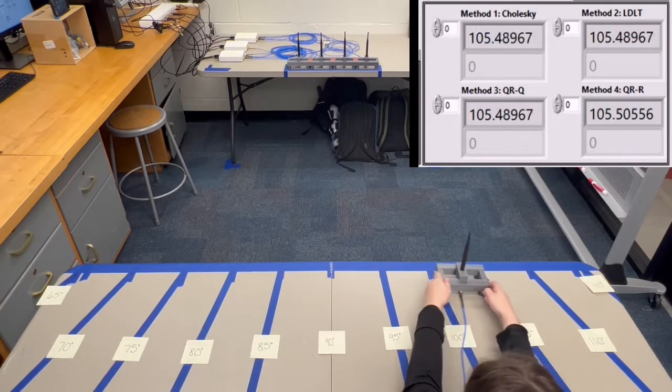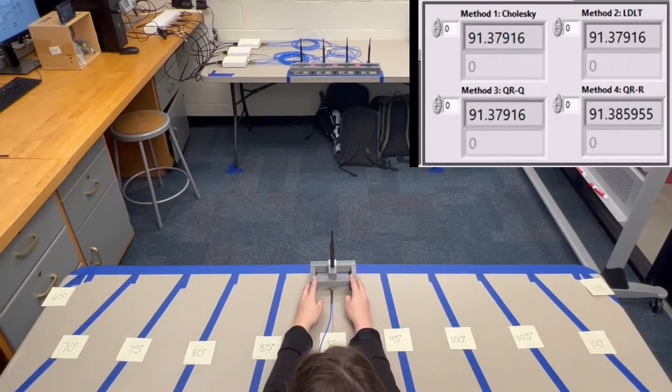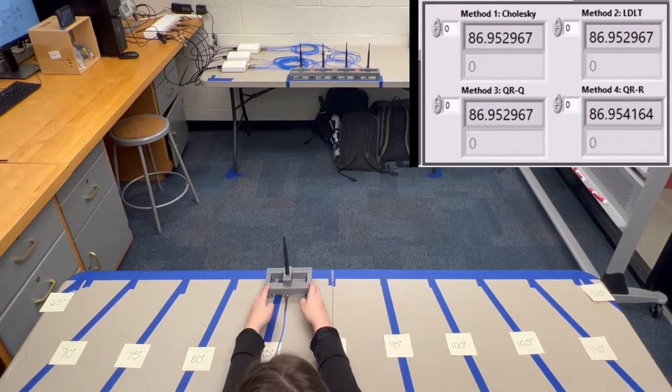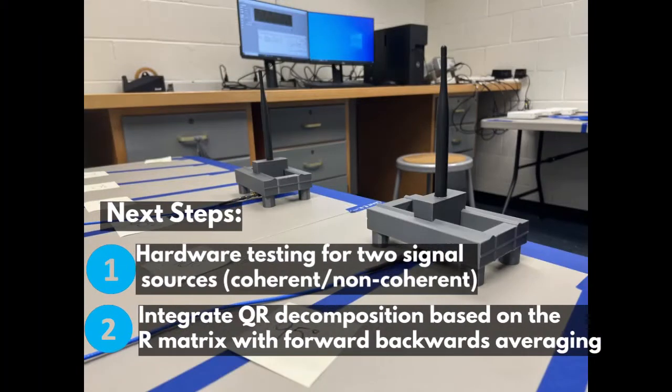Due to this, as well as our limited testing environment, we believe that we are dealing with the multipath and reflections of the signal within the room. Our next steps are to reduce this, as well as introduce a second transmitting signal and introduce a final direction of arrival estimation algorithm.